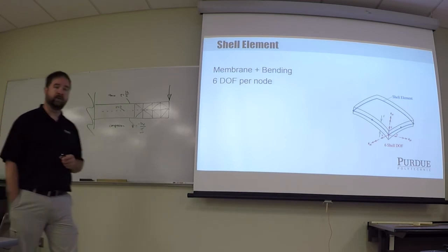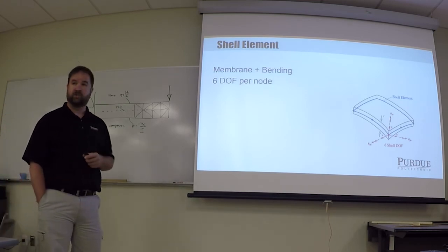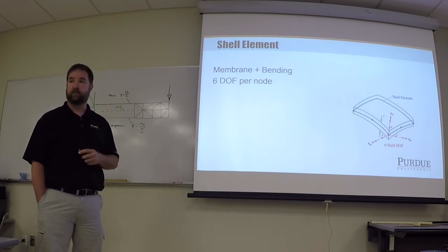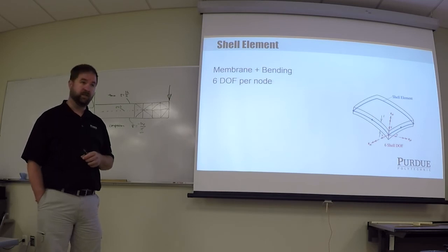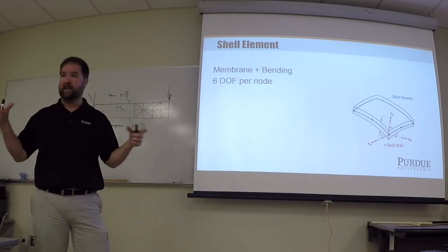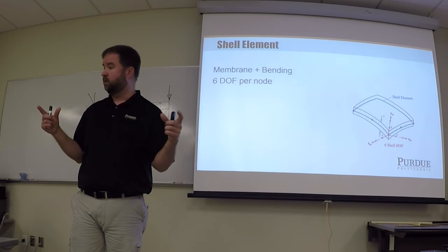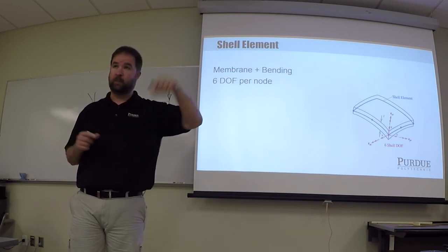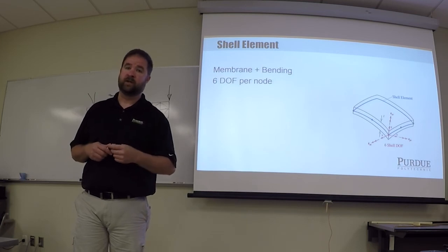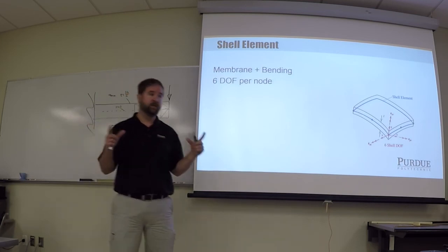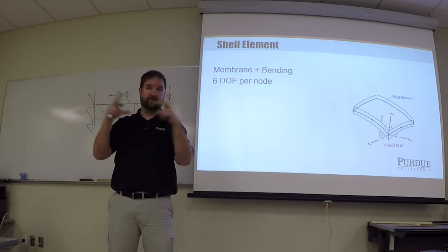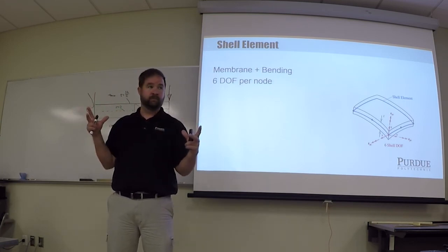What we are really going to be using, I call this plates and shells. In almost all cases, we are dealing with shell elements instead of plate elements. The difference between the two is plates are in-plane loading only. Shells have the addition of bending, which would be a perpendicular force. So if I go back to my balloon analogy, a balloon is in-plane only when I just have the pressure inside the balloon. Okay?